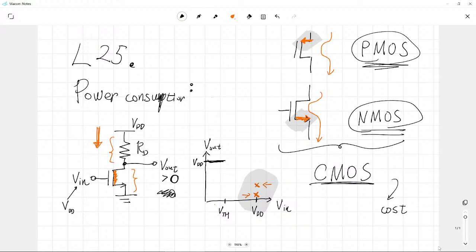Then how large is it? So that can be given by just VDD multiplied by the amount of current. So what is the amount of current in this case? Of course, here we have to have current, and that current would be just drain current of our transistor, or also the current of our resistor. Yes, in this case, drain current and the resistor current are the same. So are you with me about this point?